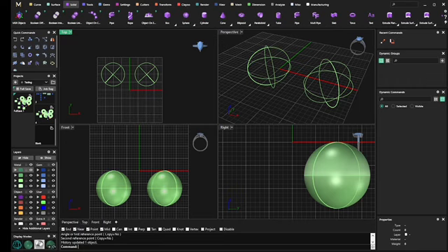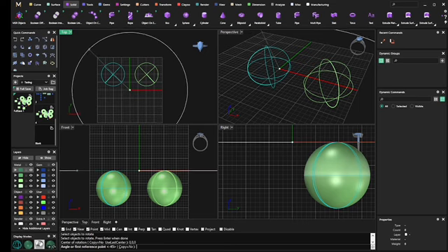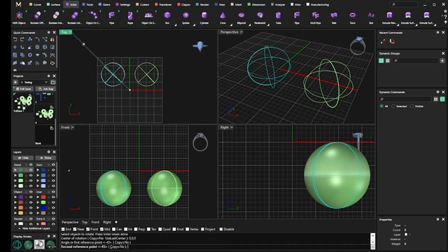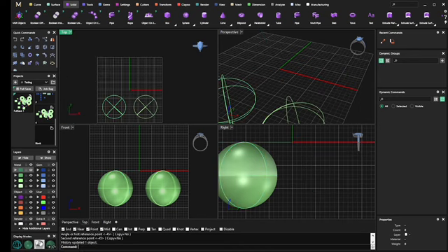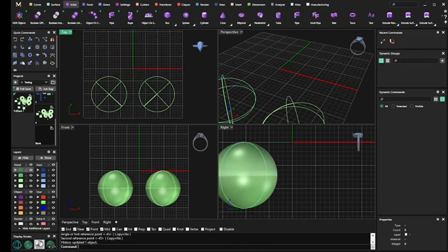Let's do that again. I'm going to right click on my mouse and it asks me what objects. When I right clicked on my mouse, it activates the last command that I did. This is the object that I want to rotate. So I am going to press enter by right clicking on my mouse. Center of my rotation is F4. I'm going to lock it in at 45 and I am going to come down here 90 degrees away from that. There we go. It moved again.